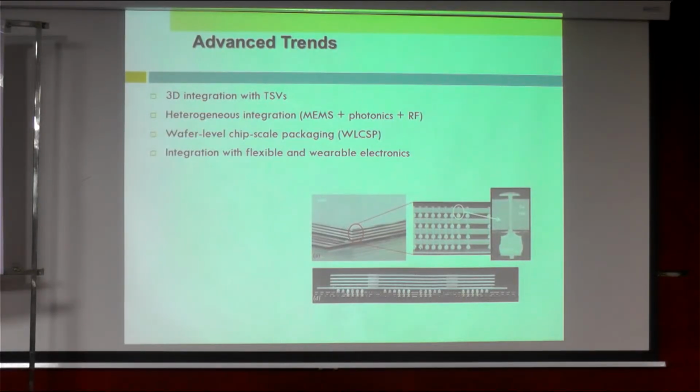TSV is considered one of the advances in MEMS packaging and MEMS design. So you can see here, you can stack a lot of chips and also devices. Let's say this is just 200 to 300 micrometer, so you just stack it up, rather than connecting at the side or with some other means of connection, just stacking with a few micron thickness between the solder balls here.